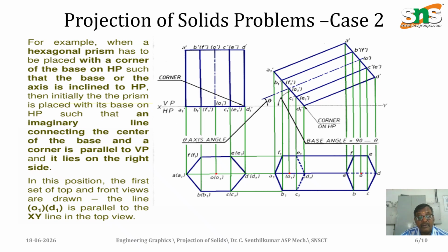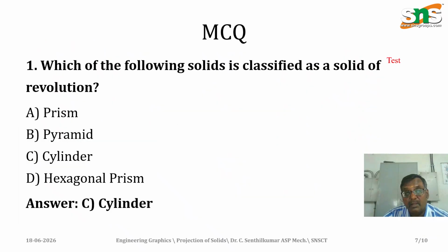After drawing that, what do we do? Based on the arc method, we draw this rectangular prism here, draw the line. We project downward A, B, C, D, E and A dash, B dash, C dash, D dash, E dash and A1, B1, C1, D1, E1. All the lines we project downward. Here also in the top view, we project horizontally. Wherever the concerned points are intersecting, there we get the hexagonal values of side 1 and side 2. Side 2 is visible because in the top view it is visible. The top one was not visible.